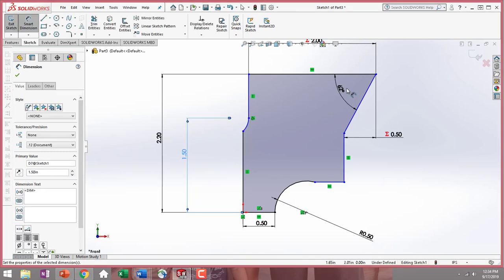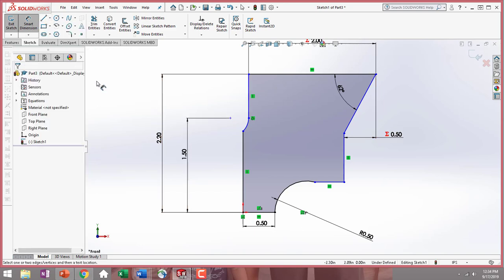I just want to remind you, when you are doing angles, select the line segments you want in between those angles. If I were to have a rectangle line out here and a top edge right here, I would also want to create a midpoint or a hidden line using my line conventions of center lines right here. And I would sketch my dimension and angles from that. Also create relationships. So you can always use your center lines. It's just used to help you sketch, and it doesn't affect your design, especially if it's inside of one another.